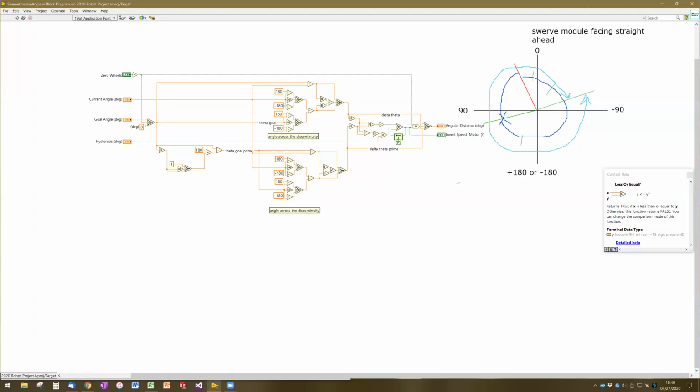So we've used hysteresis on the auto shifting from last year. So there's a very similar problem. If you wanted to auto shift at 5 feet per second, then as the robot passes near 5 feet per second, we would have a risk of it oscillating between being in high gear and low gear as it's right around 5 feet per second. So what we did was we said, okay, if you are currently below 5 feet per second, then I want you to switch into high gear once you get to 5 feet per second.